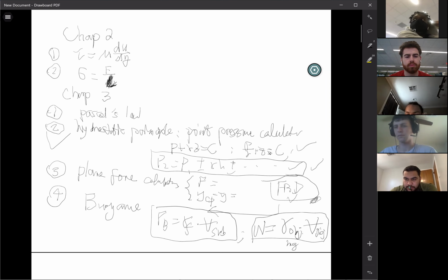g is already given. Why not just use that equation? mg is okay, but m is still rho times volume, then times g. Basically they are the same thing. So remember, if you remember these two equations together, it's easy, because both of them are gamma times volume, just a different gamma and different volumes.